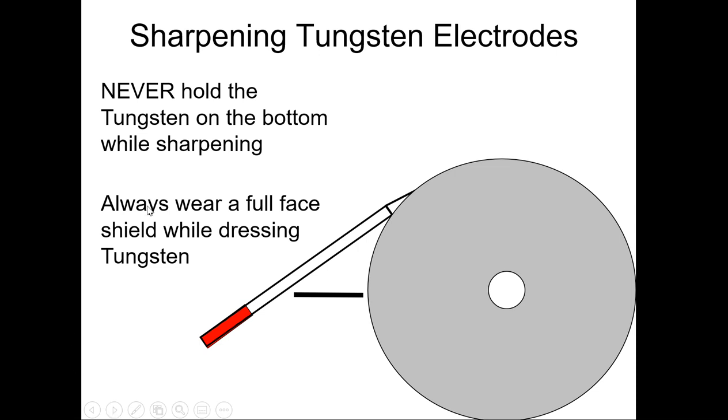I'll make a quick little point here. I've had a few people go to a grinding wheel like this, and they've actually bumped it and ended up pushing it right through their hands. So I always tell people, do not put your hand on the bottom of these. And I will demonstrate how to do this. I will wear a full face shield while I do it, because it's popped up and hit many people in the throat.